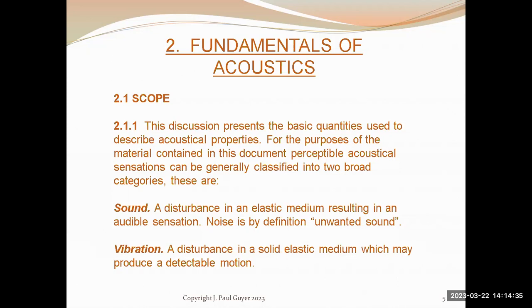And again, using the example of a fan room in a building, you've got a fan in there, it's rotating, it's bouncing up and down, and it's shaking the building, the columns and the beams and the deck plates and this sort of thing. And that is also something that has significant potential to annoy the occupants of the building. And so you need to address those vibration issues if that is appropriate in your design situation.